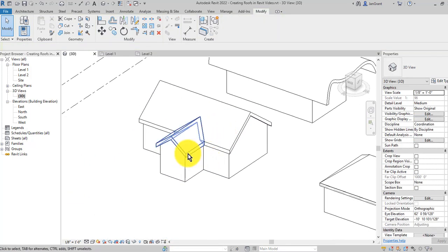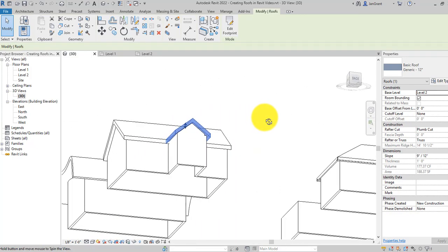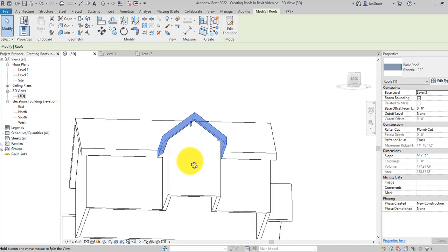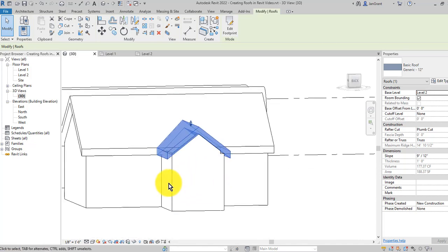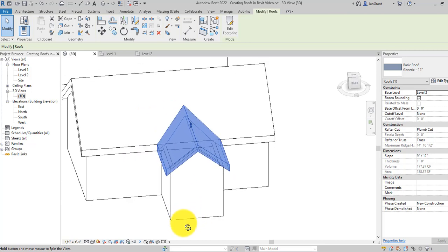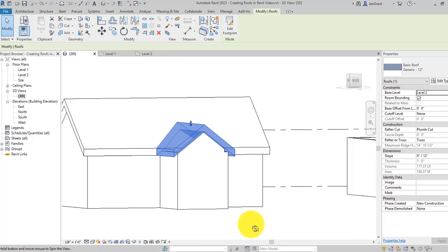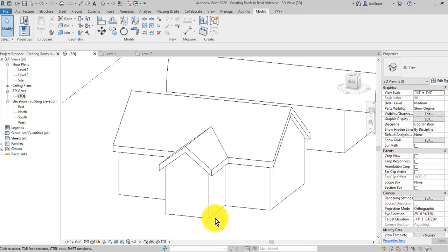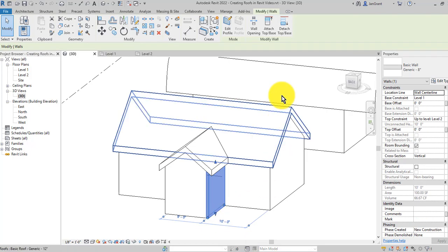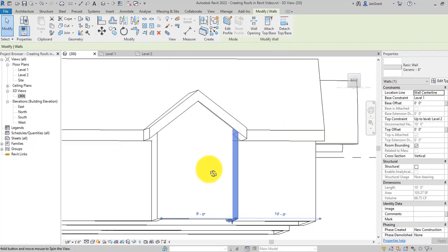And I did say also, if you select an object before you orbit, it makes it a little bit easier to orbit around. I did notice, and this happens sometimes, because these two sides did not extend to the roof, I will pick those two, or else I'll have that little piece right there that's kind of annoying sometimes. So I'm going to select this wall, pick attach top base, and pick the roof. There it goes. It's extended now.